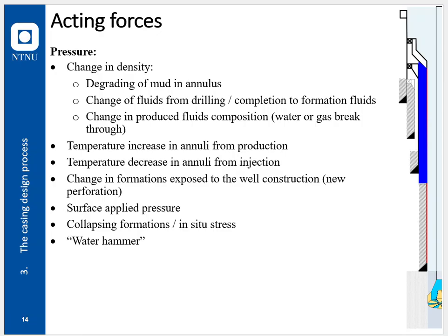So that is something to mark very well somewhere in your professional ledger: if you're perforating, say, and doing a through tubing drilling situation and so on, the original casing tubing design needs to be revisited and upgraded to accommodate new pressure regimes and uses of the well.